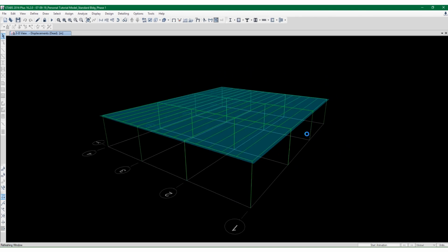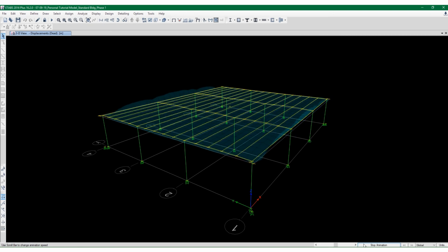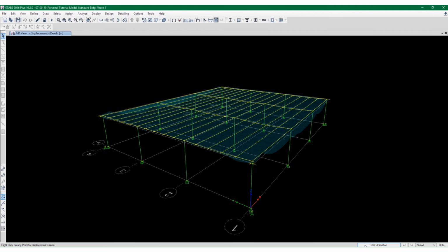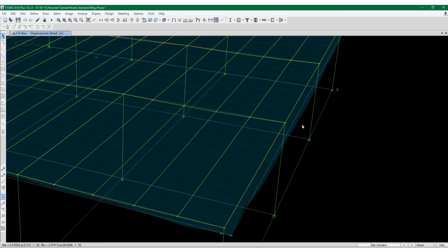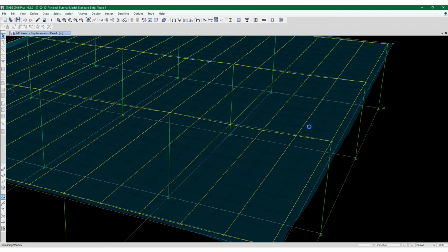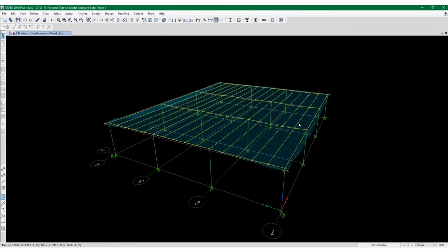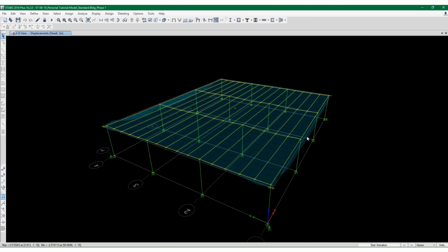And with the deformation, because this thing is scaled, you're not seeing the results that you would normally see at this particular scale. You have to modify and see what else is going on, but if you change the scale and increase it, then that changes the scale on the deck. You have to turn the deck off and take a look at some other things. So it's a hassle, right? All this because of meshing a semi-rigid diaphragm with essentially small structural stiffness properties, relatively speaking, small for decks.